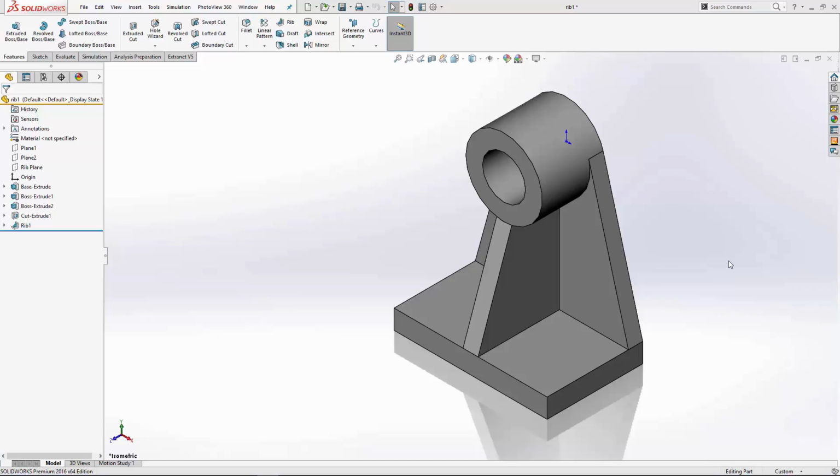Planes are often used when using a loft feature, as you can do an offset from a surface, and you can have your two different sketches loft in between. They're also really quite useful for a mid-plane, when you want to do a mirror and keep things symmetrical. I'm just going to show you the tool, how to use it, and a couple of the examples.